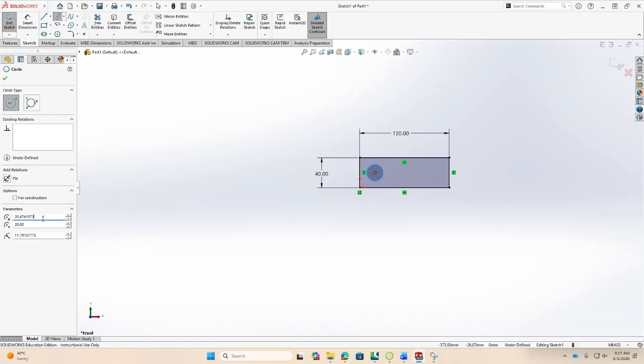As far as the x-axis is concerned, it can again be at different locations. Again, I'm not giving you in the problem any specific place, but based on a rule of thumb, you should typically keep the edge of the hole you draw away from the edge of the part by almost 1.5 times the diameter.